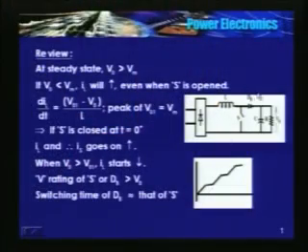So in other words, the switching time of S and DB should be the same. Otherwise, in other words, DB should be a switching type of diode. Okay. Whereas the rectifier diodes at the input side, the bridge, you can use ordinary rectifying diodes. Okay. So DB should be a switching diode, a fast recovery diode, whereas these four diodes could be of ordinary type or ordinary rectifying types.